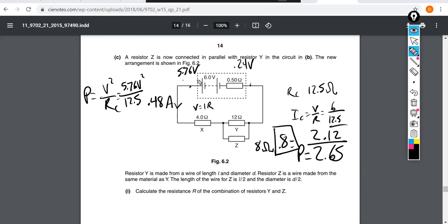My initial thought with this was, once I know the voltage here, I could calculate how much of this voltage drops across this, and then I know the remaining voltage, and I could use the same V squared over R for these resistors. But again, if all we care about is the total power in the external circuit, we just have to be mindful that there's all of the volts available for the external circuit, since we can subtract away the lost volts.